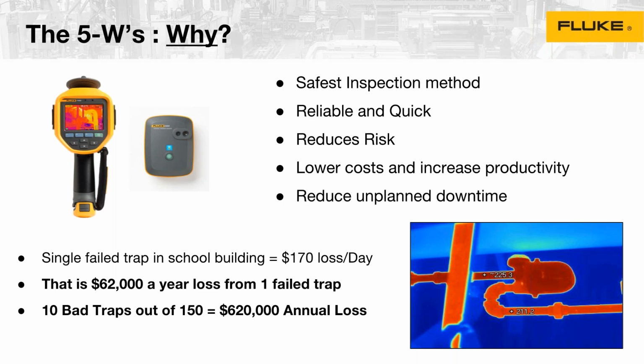Obviously, it reduces the risk of you being in danger, it lowers the cost, and tends to increase productivity. What I mean by increased productivity is that your technician or reliability engineer spends less time trying to figure out an issue, and if you have an established route as part of proactive maintenance, they can use this camera and move fairly fast. So you don't have to spend so much time on one particular asset and then spend double the time on the next one. And to a certain extent, you can prevent problems, and the idea is to move from reactive to preventive and proactive maintenance.